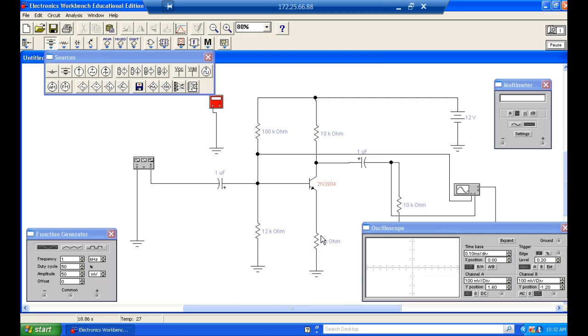If you got what we call a short, and this is the problem with bipolar transistors, is they can go bad different ways. A resistor will not short. I've never seen a resistor short. I've seen a resistor get shorted around when people do something stupid, right?